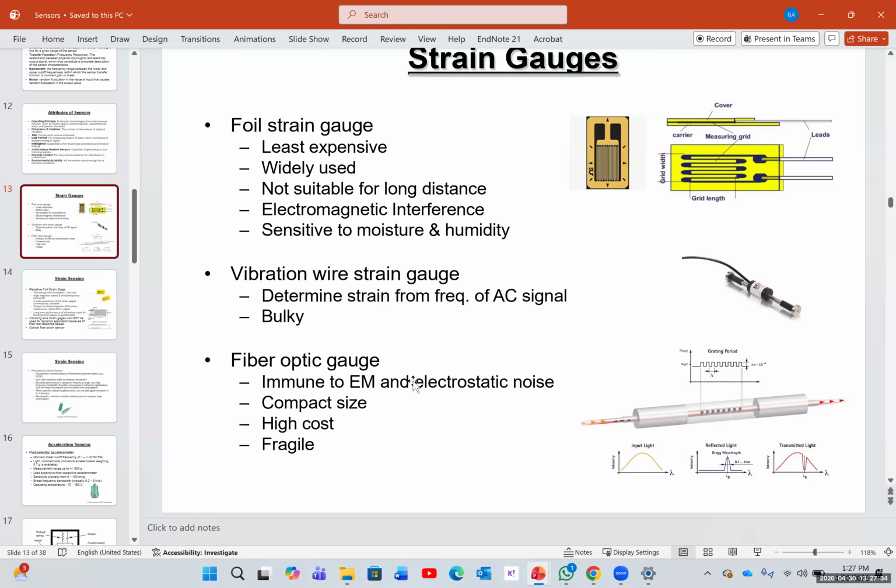And what we do in the receiver, we just use what we call an envelope detector, which is technically a diode, resistor, and a capacitor. And we'll connect these dots. It's like an analog to digital, and we extract that. So in the output, we extract this, and then we push it through an amplifier, and we can hear it. So by slightly changing the frequency, we can go to different stations. So from 90, if you go to 100, you can pick up 100 megahertz frequency or 150 or so on. So AM looks like this.